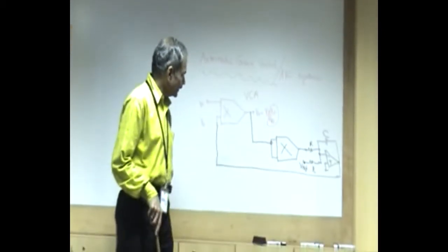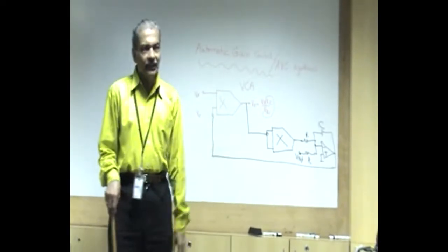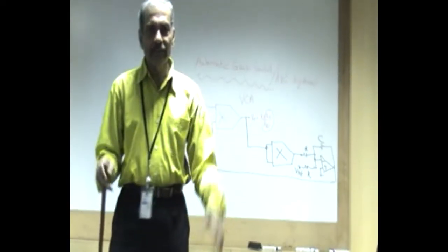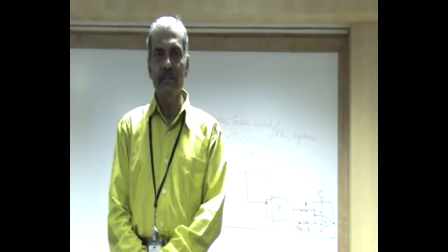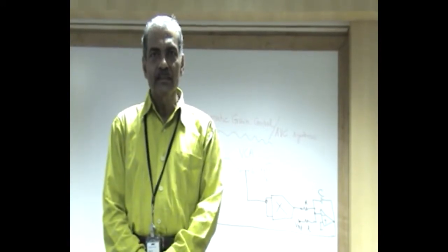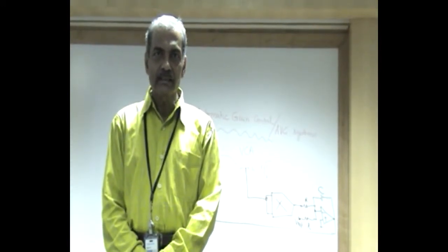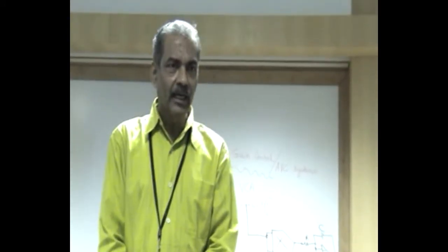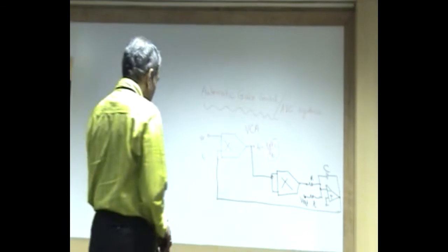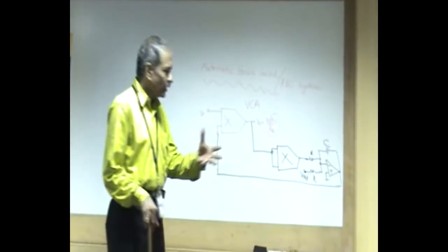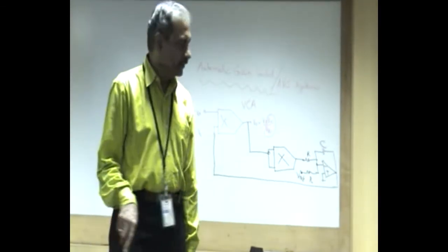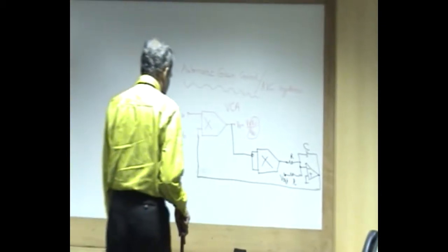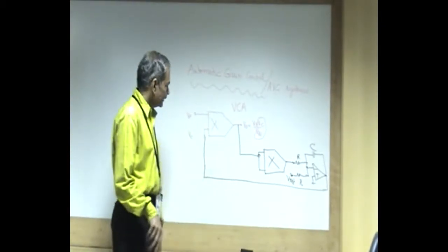And in the case of analog signals like IF, RF, etc., the magnitude of these IF, RF depends upon the sensitivity of your antenna and the front-end electronics, the gain, etc. And the signal received keeps on fluctuating, and therefore the output amplitude should not keep varying, okay, with this kind of thing. So we want to make that constant.